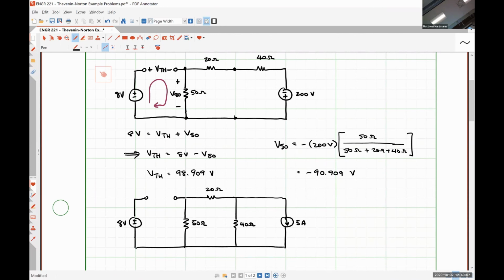So to determine the Thevenin resistance, Thevenin's theorem tells us that we need to be looking at a dead network. A dead network is a network where all of the independent current and voltage sources have been turned off. We always have to leave the dependent sources on, but in this case there won't be any dependent sources, and we won't actually start working Thevenin and Norton circuits with dependent sources until next Wednesday.